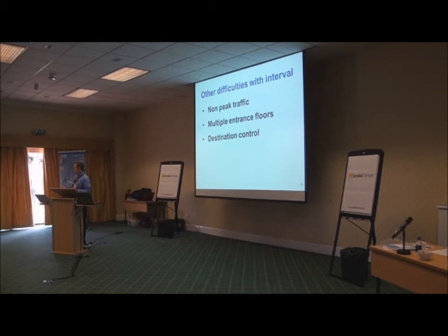And then you get destination control. And when destination control was first sold, people still reported the interval, but actually you didn't get into the next car to depart. So the interval was actually a meaningless measure of quality of service in the context of destination control. So interval is a great measure, and it's a great measure in a round-trip time calculation. But when you start using it in simulation, it starts to get really confusing, which is why I encourage people when they move to simulation to start thinking about waiting time and time to destination and all these other parameters.